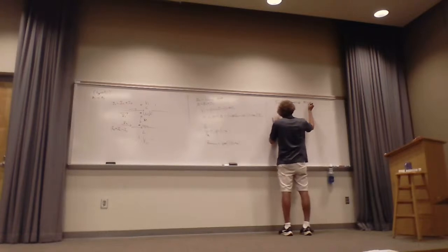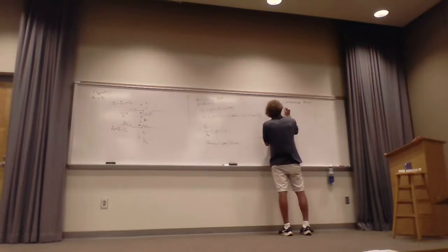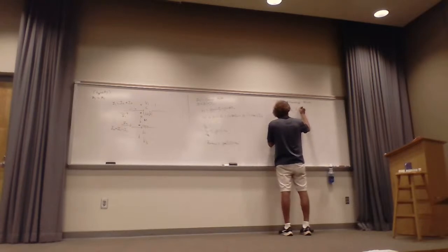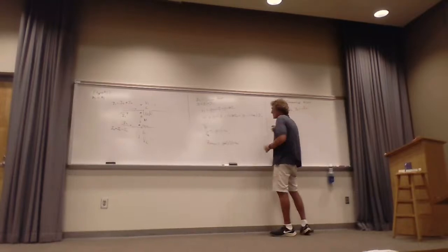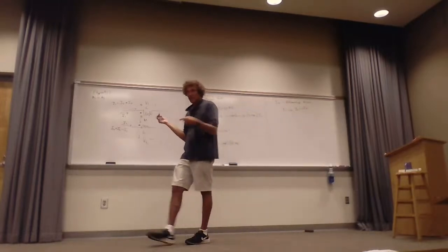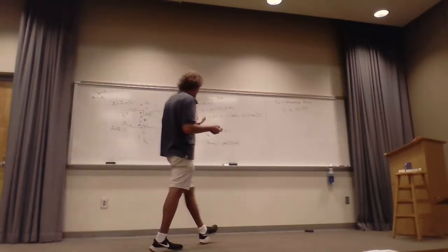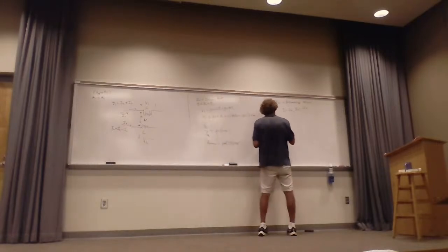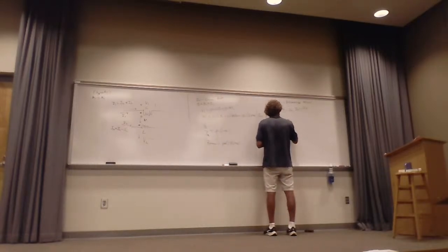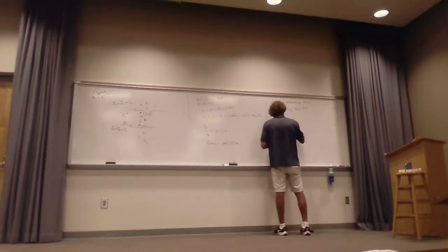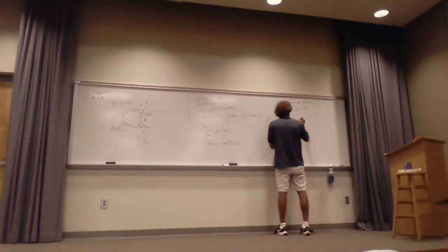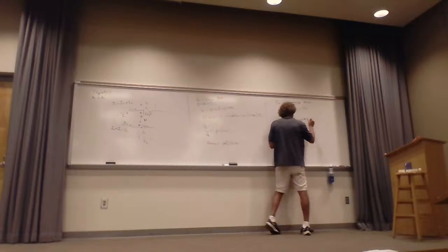And lo and behold, when I do that, I say that I1 is equal to I differential and I2 is minus ID. Do y'all follow me on that? Because it's going in the opposite direction, right? I1 and I2 dictate the directions. So now I look at V1, and I have V1 is equal to j omega L times I differential. But this is minus, so then it's minus j omega M times I differential. Y'all follow me?